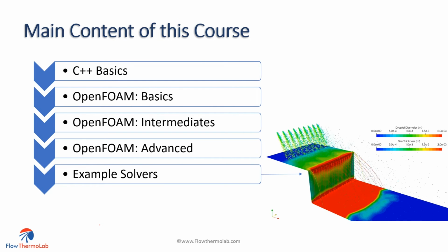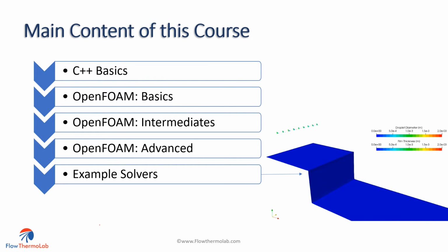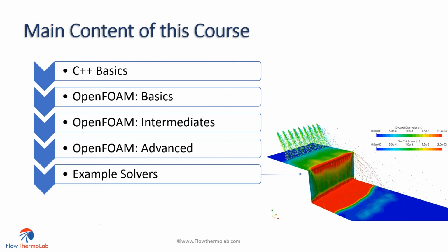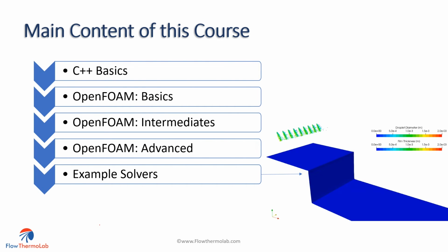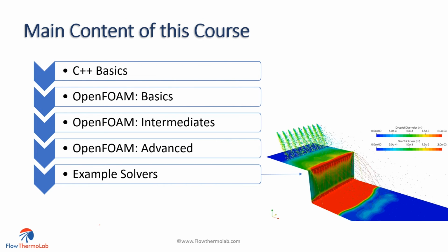We're going to be looking at introducing further complexities such as new submodels that haven't been implemented in OpenFOAM before, such as a new droplet diameter distribution for our spray injection based on a log Rosin-Rammler distribution, or a completely new film stripping criteria built from scratch, or a complex edge separation criteria which allows for a proportion of the film to separate from the surface as droplets, whilst a proportion of the film remains attached to the wall.